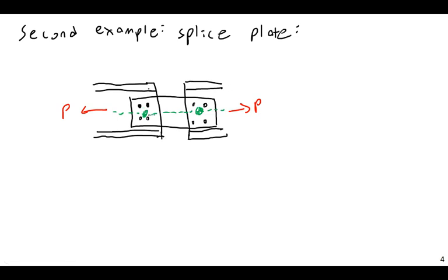And so ideally, I would make it so the centroid of my bolts, the centroid of my loads, and the centroid of my wide flange shapes all line up along the same axis. If I do that, I avoid any kind of eccentric loading and any kind of induced bending because of that. But sometimes that's unavoidable, but we won't worry about that right now. There are cases where you simply have to design eccentric connections because of limitations in geometry. You can't always do the ideal case.